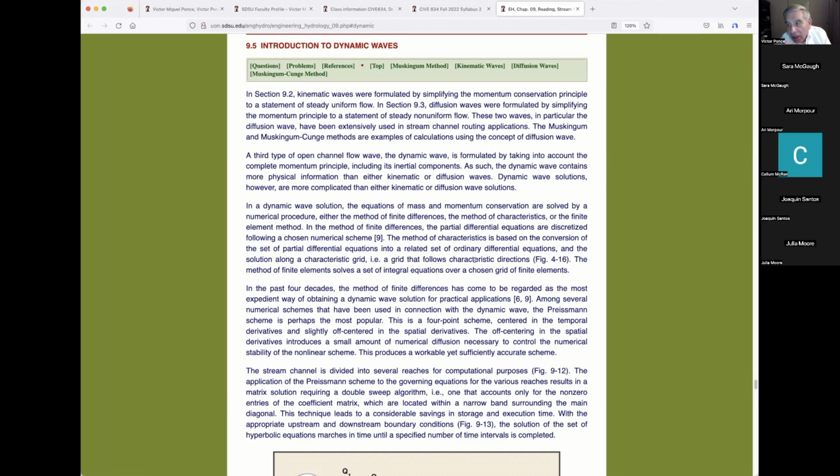The next type of wave is a diffusion wave. The diffusion wave diffuses a little bit. The British have said in the year 1975, with their experience, that if within one period of propagation the wave diffuses less than 30%, it is a diffusion wave. And then by exclusion, if a wave diffused within one period of propagation more than 30%, it would be a dynamic wave.